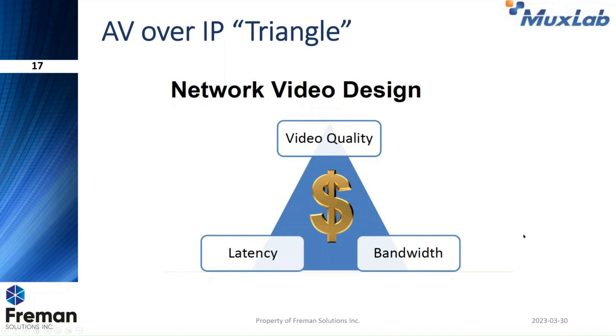However, if I'm willing to go with an H.264 system with extremely low bandwidth, and by the way, remember that you watch television at 3 megabits per second with H.264 compression, and it looks pretty good, right? So if you're willing to do that, the video quality will still be acceptable, but it will be less than with the previous case. However, the latency will be a little bit higher, so you have to say if you can accept that level of latency, but you're going to be spending less money than with the previous solution. So there's no two ways around it. These three parameters are interrelated, and the amount of money that you're going to spend is going to depend on the decision that you make related to those parameters.